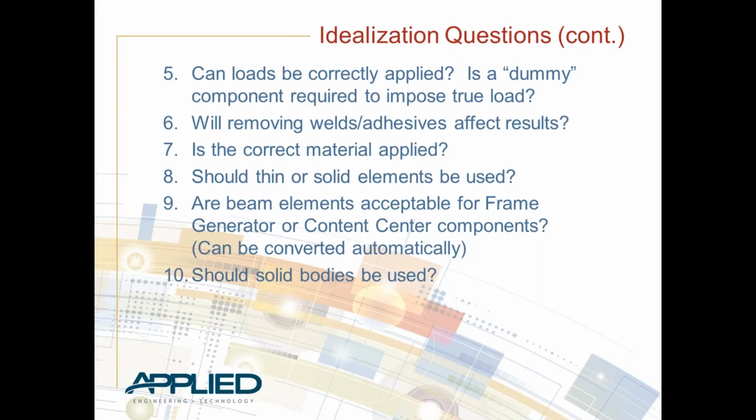Will removing welds, adhesives, whatever other types of bonding you've added to your models, affect our results? A lot of times, welds can be left in, and as long as they've been applied correctly, it can really change how forces and stresses react in a model.